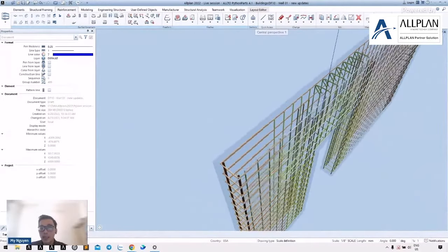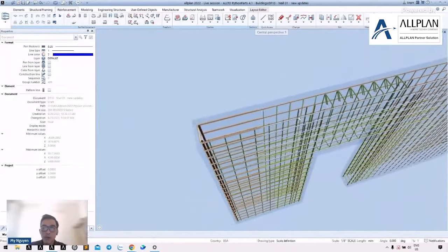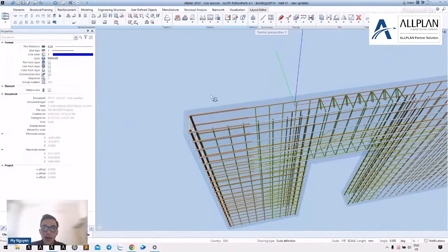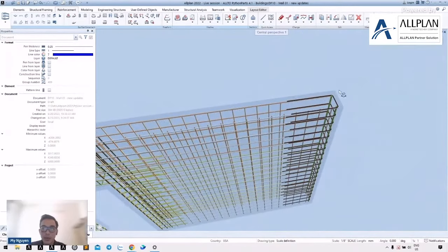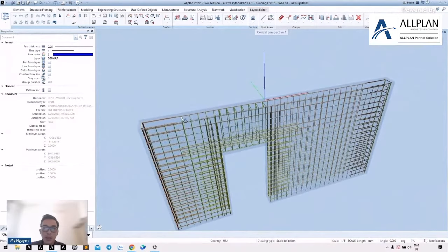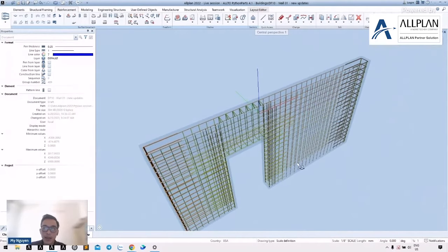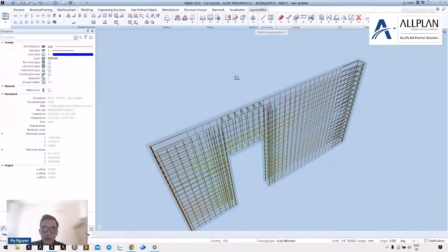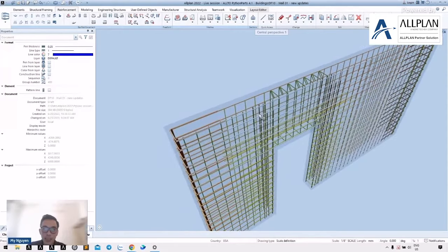When we click this option, we will remove the vertical rebar at the corner stirrup here, this position and this position. So when we put this layer of the reinforcement first, and then we put the rest layer with the corner stirrup here and here, we can avoid the clashing between them.